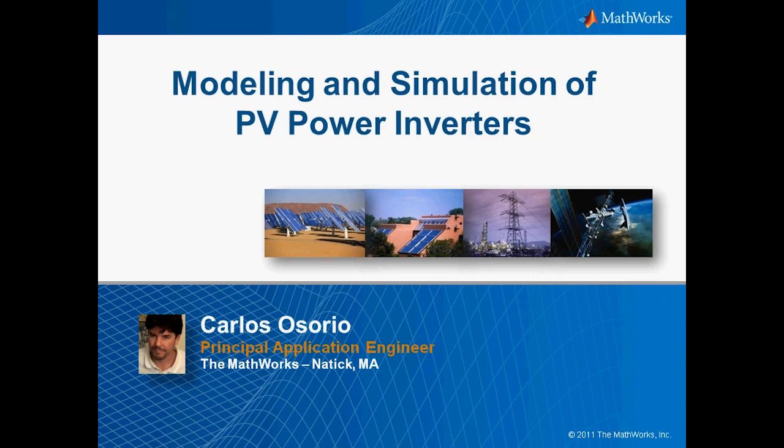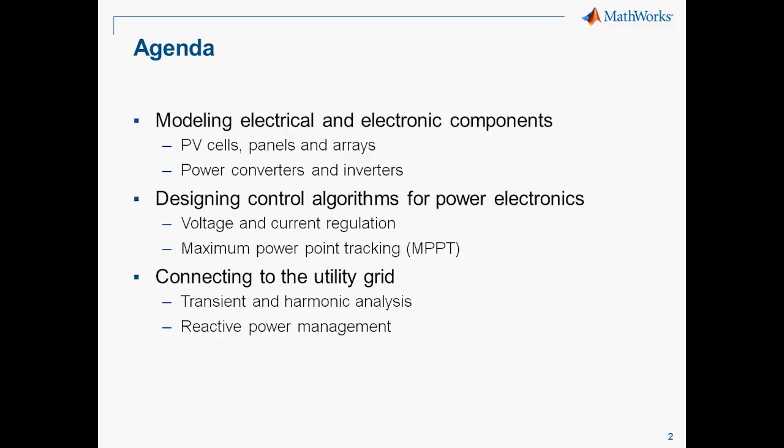So first, let me start by taking a look at the agenda. We're going to cover basically three topics. First, we're going to start with modeling components such as PV cells or panels, or combining them into arrays. And also we're going to look at the power electronic converters and power electronic inverters. In the second section, we're going to talk about designing control algorithms for those power electronics. We'll look a little bit at voltage and current regulation, and we're going to focus on maximum power point tracking, which is very important for photovoltaic systems.